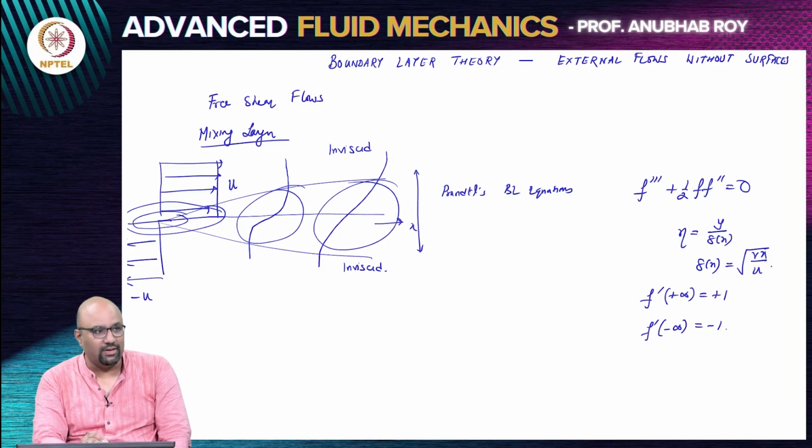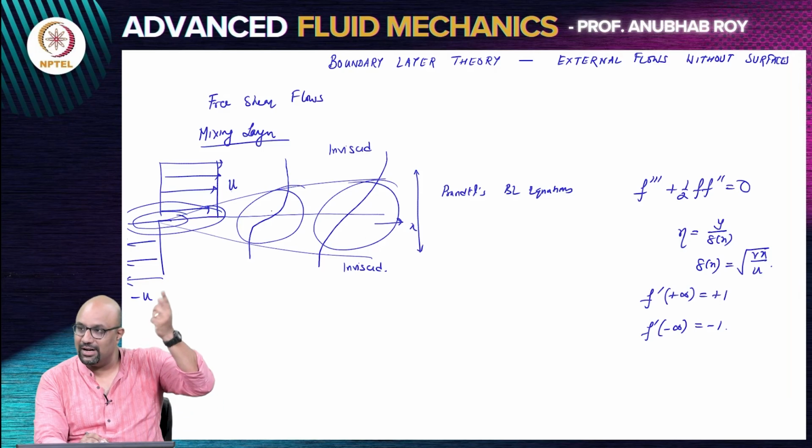The approach of solving is again going to remain numerical in this problem, it does not change, but the basic concept of boundary layer is now applied actually inside the fluid. So it's like an interior layer. Even though the term that we are using is boundary layer, if you think of it very formally, the region where you are matching viscous to inertial forces is happening somewhere inside the fluid. It's not happening at the boundaries. The boundaries are where viscous effects are negligible here, because the boundaries are at plus infinity and minus infinity. So there are no viscous effects far away.